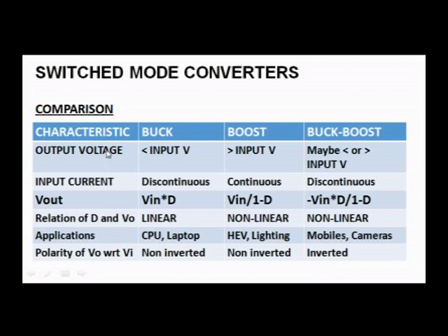And major comparison in the area of application areas, buck converter, wherein I make use of it in computers and in laptops. I told you to drive the processors, to give very low voltages to the processor, maybe 0.8 to 1.8. So, that is where buck converters are finding high usage.